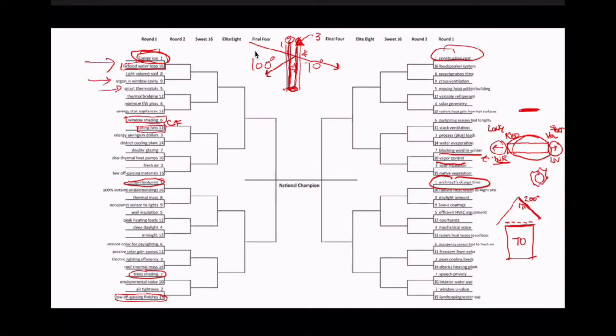By putting foil down here, you're reflecting some of that radiant heat back up, heat that would otherwise jump across from the hot surface to the cooler, softer surface. And you're doing it for almost free. You just have to watch out for moisture.